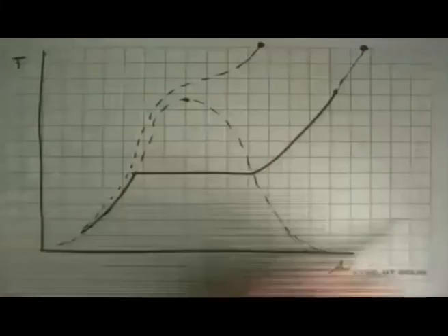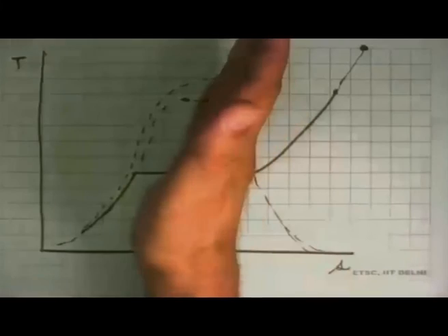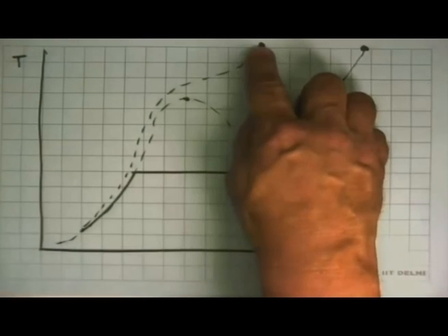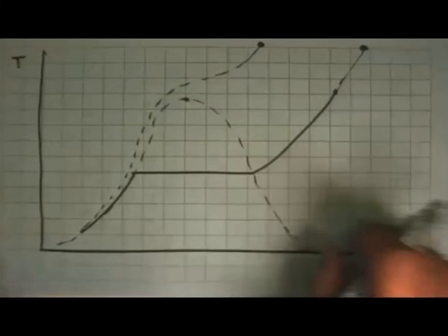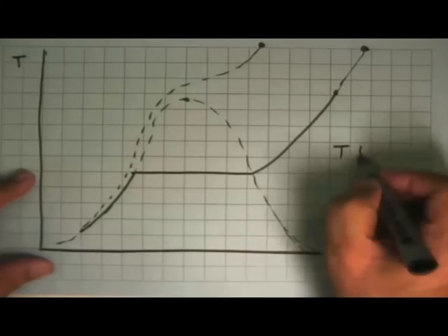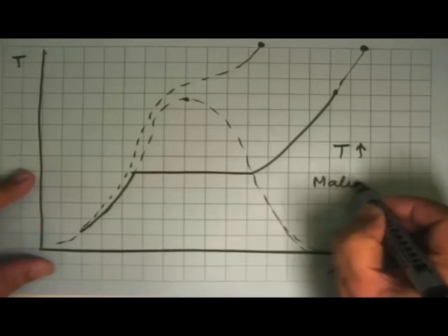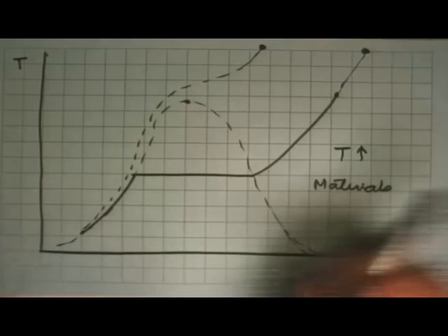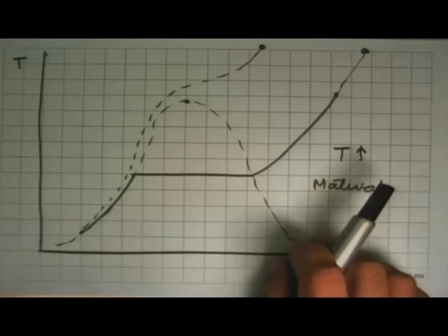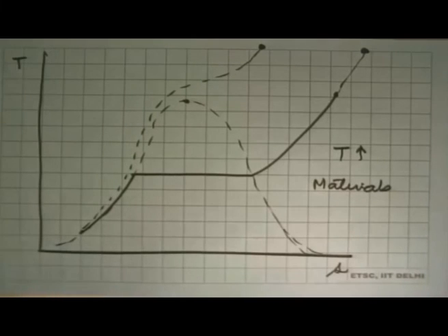So that is the reason why traditionally pressures have gone up, temperatures have gone up, and we are coming to supercritical pressures and temperatures. The limiting factor though, thermodynamics tells you can go as high as you want in temperature, but we do not have materials for making a boiler that can withstand such high temperatures at high pressures for 20-30 years. That's the challenge. Okay. So with that we will conclude this session. Tomorrow we'll look at some more of the property diagrams, take some more examples, and then we will go on to see what is ideal gas behavior.